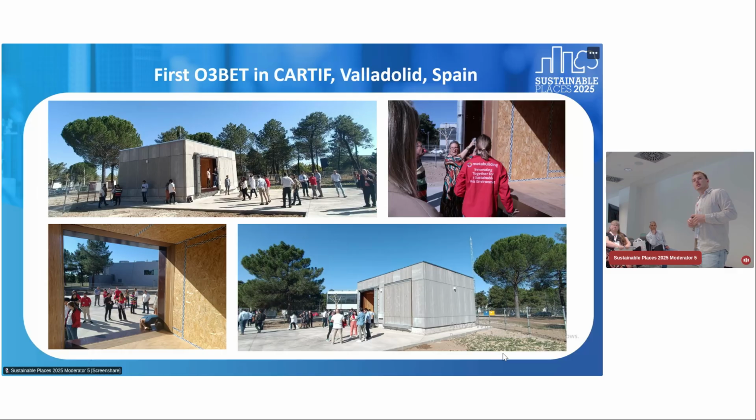And what you see here in this structure is a specific testing facility with very strict air tightness, with very sophisticated sensing equipment. And we have cells, okay? And on the top of these cells, on the external side, so you see here, there's a little bridge connecting, is where you mount a new innovative facade element. So if you want to test any type of material, any type of insulation, maybe a new type of window, you construct it to this size, you mount it, and then we try to characterize it thermally, for example, depending on the types of sensors we need, to monitor the performance of this new facade element in controlled conditions.